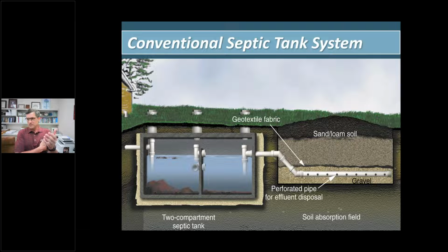And again, this is even more of the importance of knowing that we need to pump tanks on a frequency. And again, there's a great chart. I tell people, rule of thumb, every 3 to 5 years. And again, I realize there's a variation in that, but still thinking about how often you pump your tank, because you are going to have solids build up. They do need to be removed.